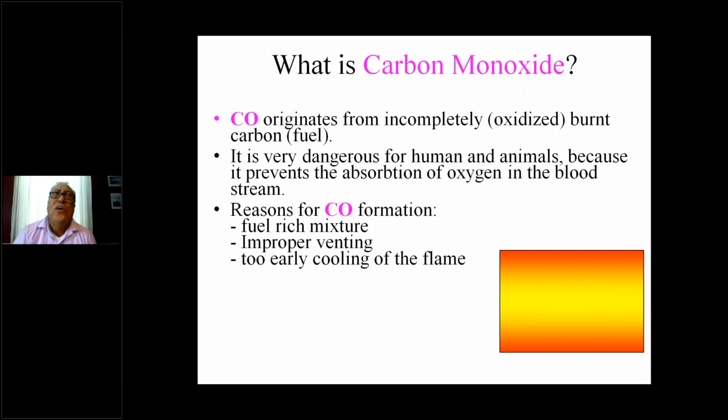One of the symptoms of carbon monoxide poisoning is flu-like symptoms. Slow carbon monoxide poisoning: you don't have huge levels in the house, but it's there, and you seem to be sick. You feel headachy, you have body aches, and you go outside for a few hours and you feel better, and you come back in the house and you start feeling it again. That's a symptom of slow carbon monoxide poisoning. Improper venting, fuel-rich mixture, all these are reasons for CO, but it is deadly.